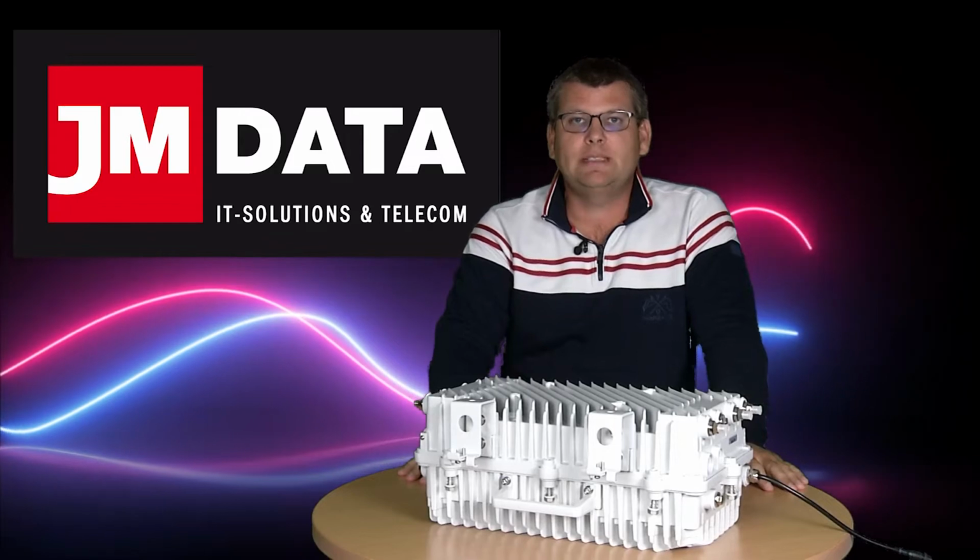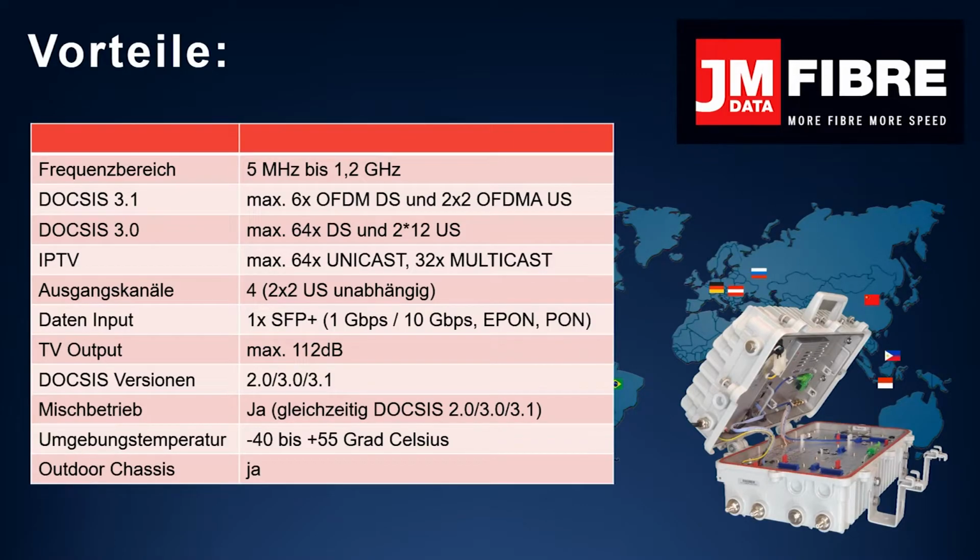And now, here are the specifications. The frequency range is 5 MHz to 1.2 GHz. This product can handle DOCSIS 3.1 with 6 times OFDM and 2x2 OFDMA channels, as well as up to 64 DOCSIS 3.0 downstream channels and 2x12 upstream channels, 64 unicast and 32 multicast IPTV channels, 4 independent output channels, 1 SFP Plus optical input for 1 gigabit, 10 gigabit and XPON connections.